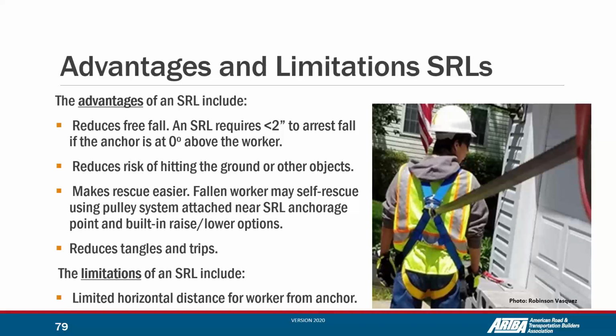It also reduces tangles and trips, because the device provides more cable according to the position in which you are moving. Some limitations are very similar to the lanyard: it has a limited horizontal distance from the worker to the anchor, basically the same as with a regular lanyard.